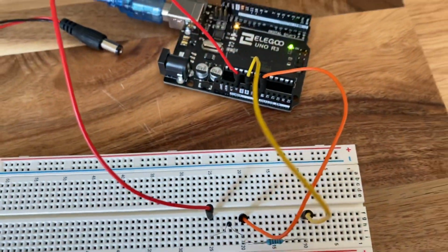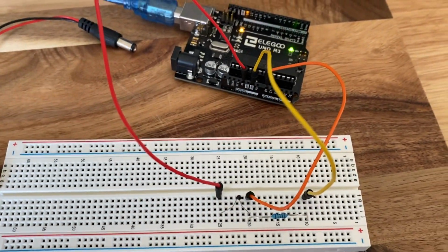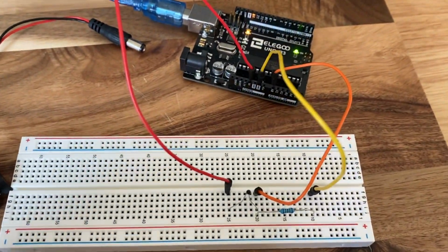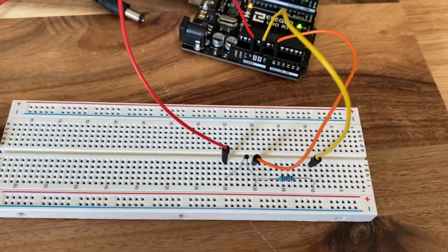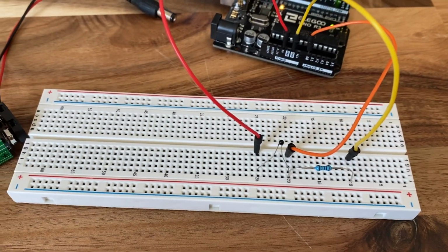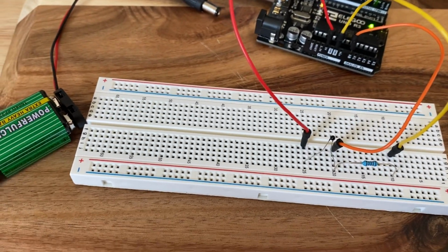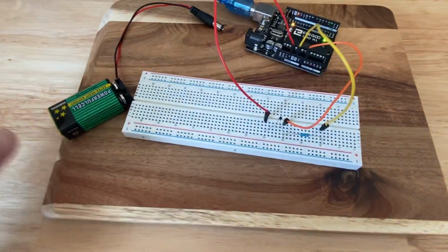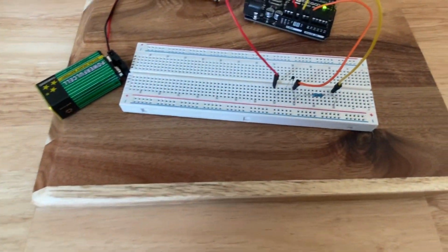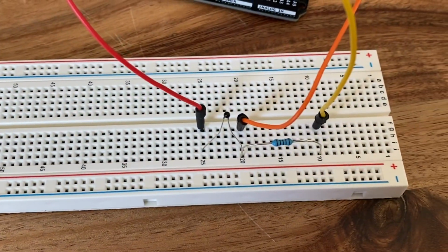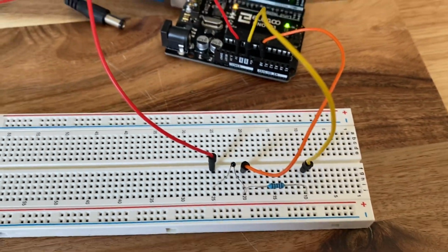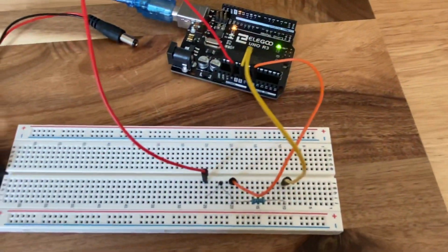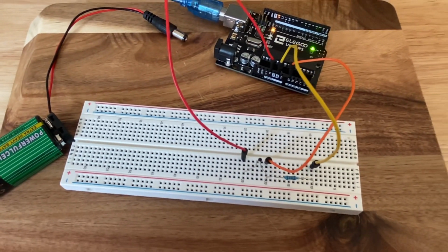After some math, that comes out to about 21 minutes of temperature recording, which is enough for me because I needed only about 5 minutes of ambient room temperature recording and then 5 minutes of recording inside the fridge. The reason I have it on this cutting board is that this is a sensitive circuit. The thermistor would sometimes fall out, and that messed with the readings on the EEPROM. So I had to keep it all together in one place.